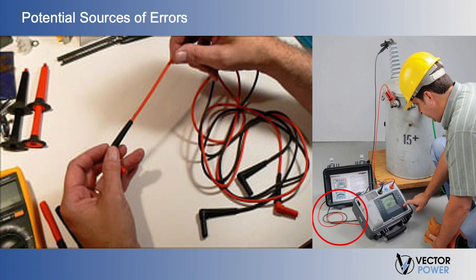Test leads should not be allowed to touch each other or any other object, since this will induce leakage paths. Sharp points at the test lead connections should be avoided, since this will encourage tracking.